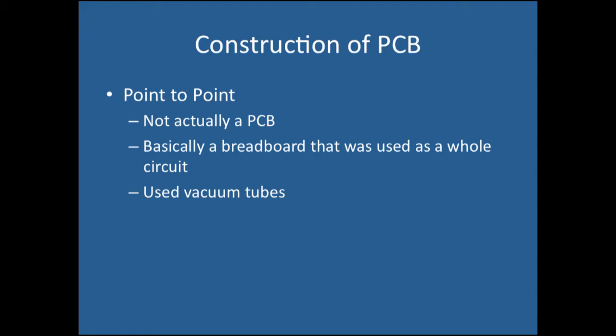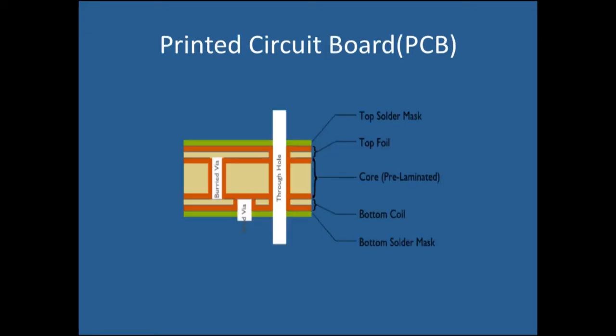Now, in order to fully understand the differences in packages, I'll have to explain a little bit more about printed circuit boards, or PCBs, and how they're attached to the microcontroller. The PCB consists of a piece of non-conductive material, such as some kind of plastic or fiberglass, an etched piece or several pieces of extremely thin copper, and a non-conductive laminate that keeps the etched copper in place on the chip. These can also have multiple layers of conductive material padded by non-conductive material connected by what are called vias that allow for a greater amount of connections in the PCB.